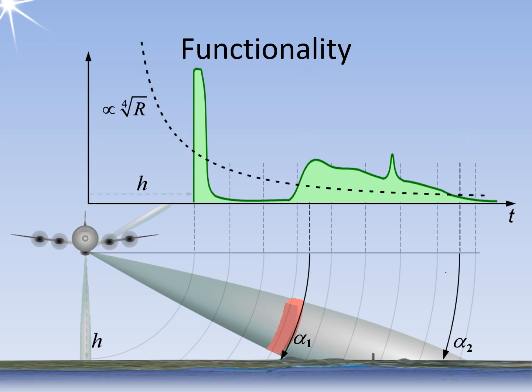The amplitudes of echo signals received in succession follow the laws of the radar equation, which state that they decrease in inverse proportion to the fourth power of the distance. However, as the distance increases, the pulse volume also increases, leading to a larger radar cross-section at long ranges. Unlike weather radar, which detects real volume targets, the targets here are not real volumes. Consequently, the amplitude, depending on the characteristics of the reflecting objects, particularly their roughness and the orientation of their reflective surfaces, decreases approximately in inverse proportion to the third power of the distance.